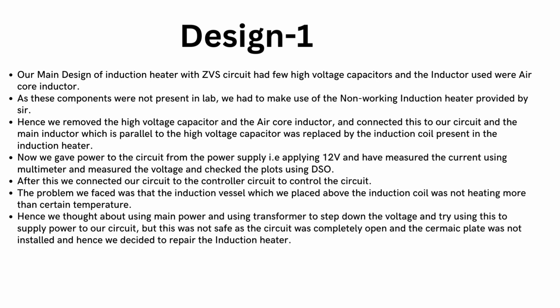Hence, we had a choice of using a transformer which could help us to step down the voltage from 220 volt from the supply power to around 50 volt, so that we can heat our induction vessel to a certain temperature. But there was a main problem that we were not using a ceramic plate, and the circuit was completely open, which could be dangerous, and the current could go very high.